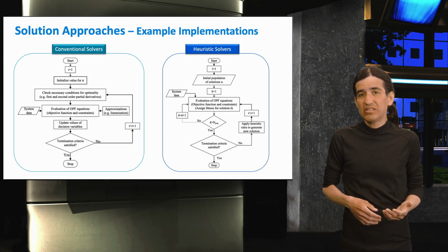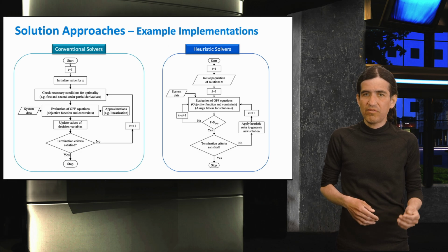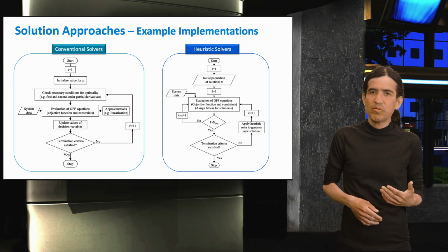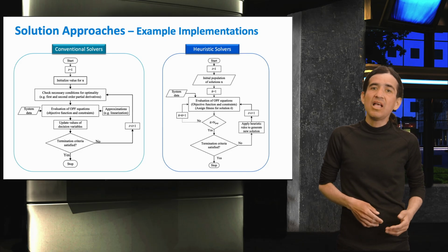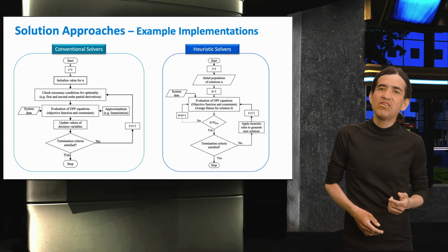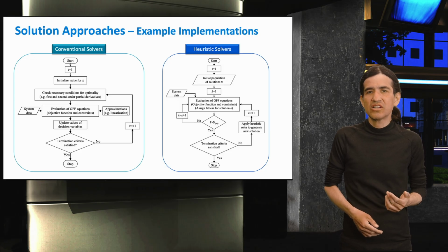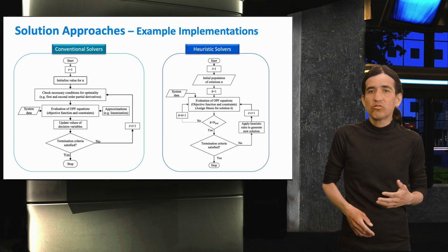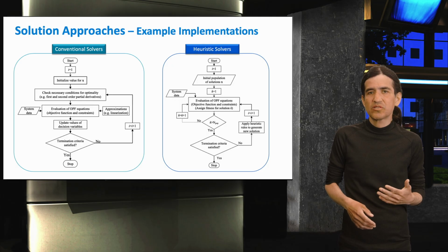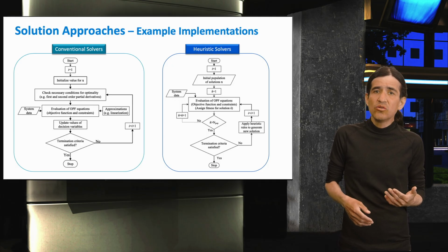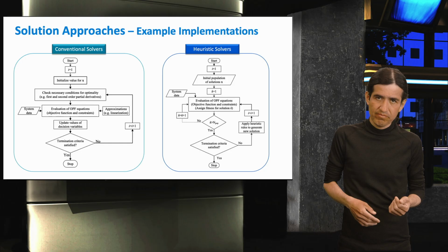Each solution is evaluated using the optimal power flow objective function, while constraint violations are handled via penalty functions or repair mechanisms. The algorithms then apply heuristic rules, also known as search operators or movement rules, to explore and exploit the search space, generating new candidate solutions.